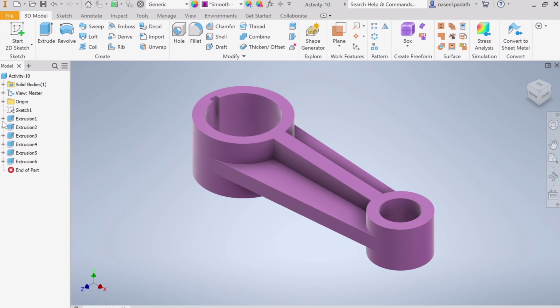Then just walk through what we did. Basically, first thing, we create this sketch, extrude symmetrically, and then these ones over there, cutting, and then the center portion, and finally we create some extra length and cut down the extra, and that's it. This is how we create. And finally the slot, a through all cut. So that's for the activity.